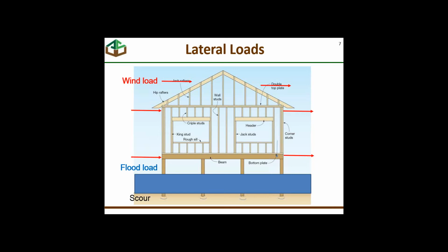If it's the corner of a building, it can take out several feet of supporting soil underneath a crawl space foundation, for instance. So scour is important because it reduces the amount of supporting soil we have, either for piles or columns or for spread footings or continuous footings like we might have under a crawl space.